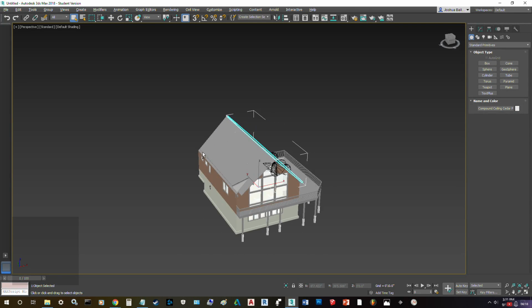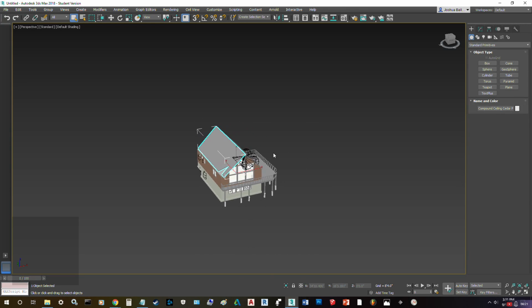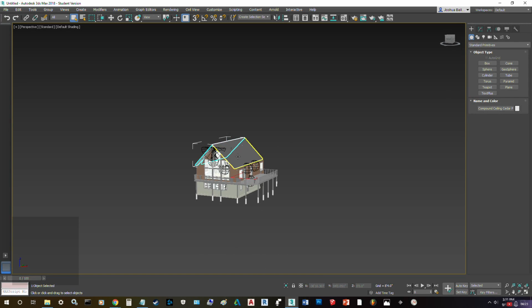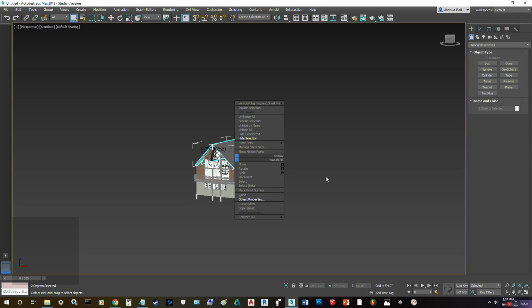I had 2 sub roofs in Revit because I was doing 2 different color paneling. Basically, I had an outer roof that had one type of shader for the actual roof color, and then I had an inner roof, which was for my panels because this house doesn't have insulation, it's just cedar planking and then a roof on top of it. And in Revit, you don't have the option of doing a UV mapping type of thing with the different pixels or whatnot, so I had 2 different objects.